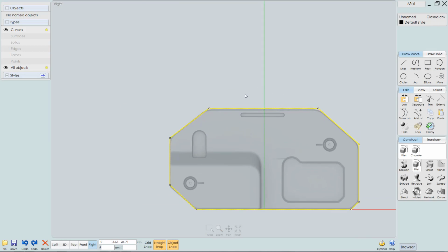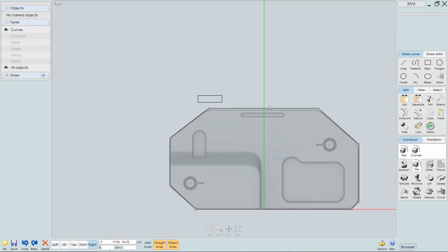And before you select new points, make sure to deselect everything, because unlike in Cinema 4D, you just need to left click on points, edges or faces to add them to a selection, or left click on them again to deselect them. And it's easy to forget that.